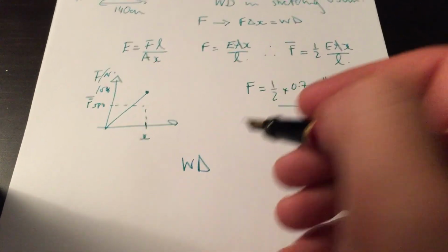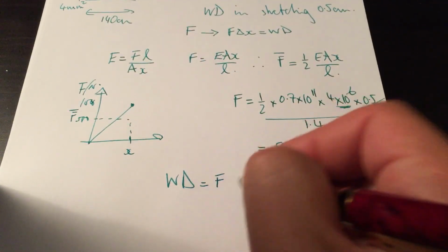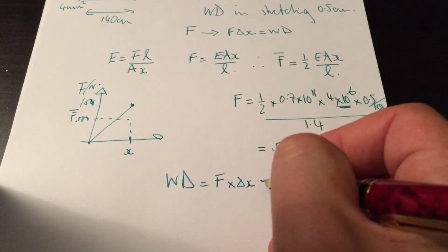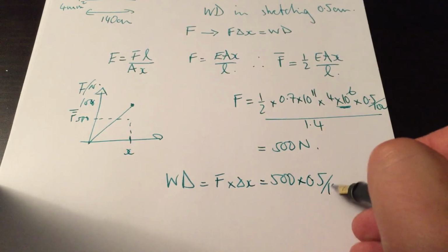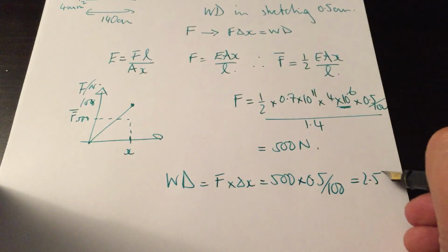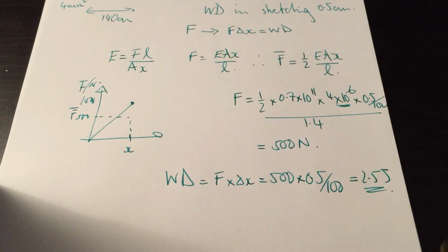Okay, so now the work done in stretching it will surely be the force by the extension, which gives us 500 by 0.5 over 100, giving us 2.5 joules. Okay, good. So, yes, I think that's all the examples you need. I hope that makes sense.